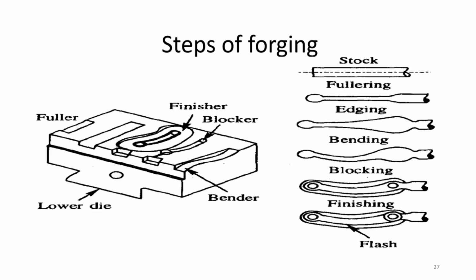For timing you need to take diffusion into account, right? How diffusion is happening in the case of carbon and nitrogen, how fast it's diffusing. So nitrogen is smaller compared to carbon, right? So nitrogen diffuses much faster, and also you need to consider temperature as well. Nitriding is performed at lower temperatures compared to carburizing.